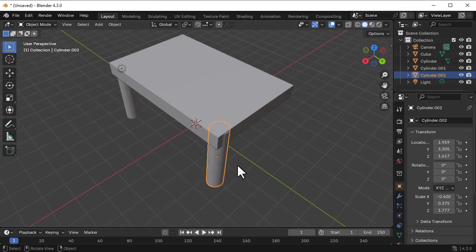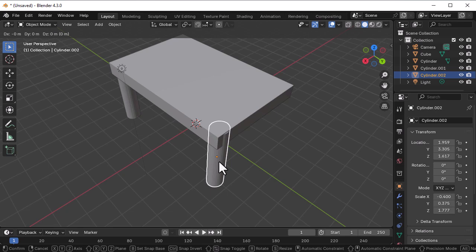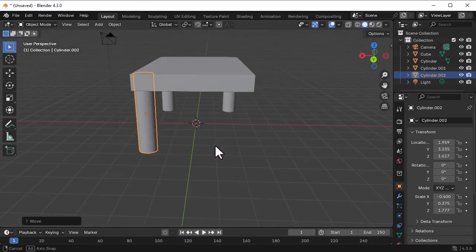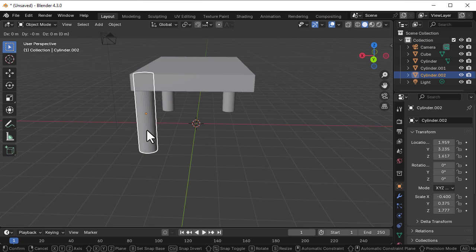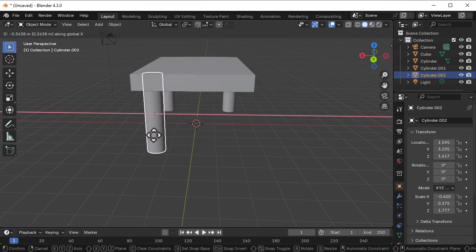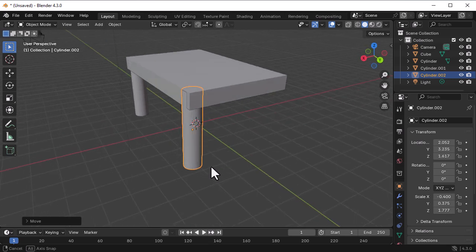A little bit it's coming out, look at here. So again select this. This axis is the green axis, the Y axis. So I'm going to select this and press G and Y. Okay, now this is perfect. I'm going to select again this axis, press G key and press X axis, and okay, I think I didn't do the Shift D, so let me just clone it.